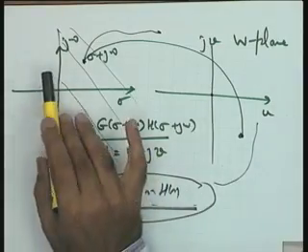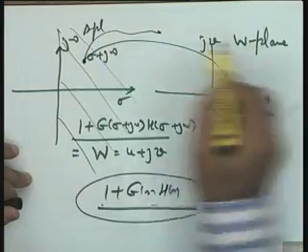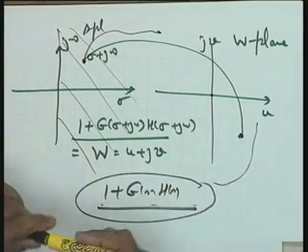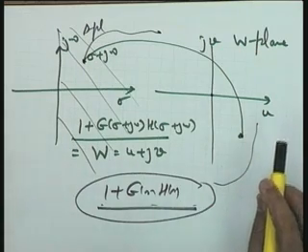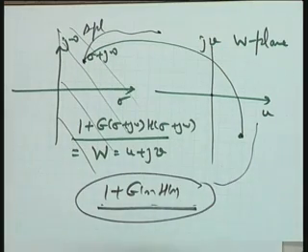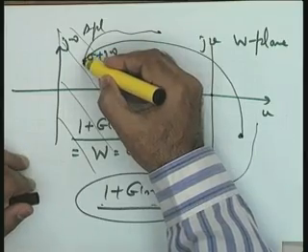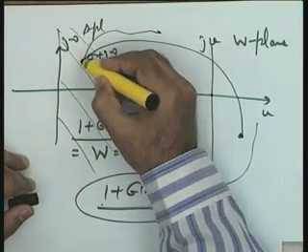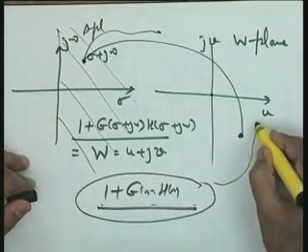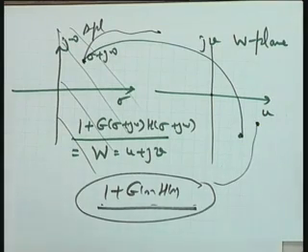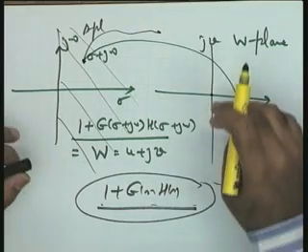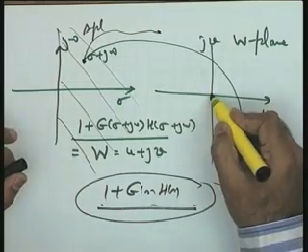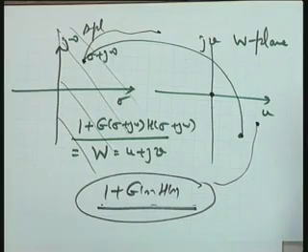Okay. So, I am actually mapping from the S plane to the W plane under the function 1 plus GS HS. One point may please be noted: what is after all your interest? You are really not interested to see, under this map, what is the magnitude of each and every point correspondingly in the W plane. You are really not interested. Your interest is to see only the behavior of the system around the origin of the W plane, whether the W plane origin is covered or not.